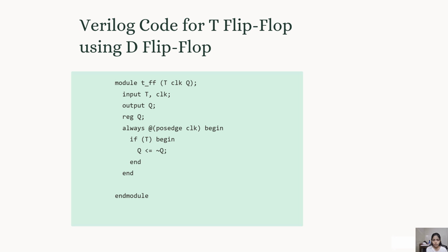Verilog code for T flip-flop using D flip-flop. Here also we first have to give the module name, then inputs, outputs and reg, always block and end module.